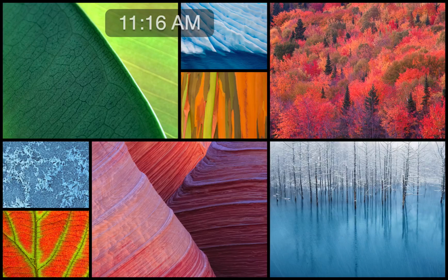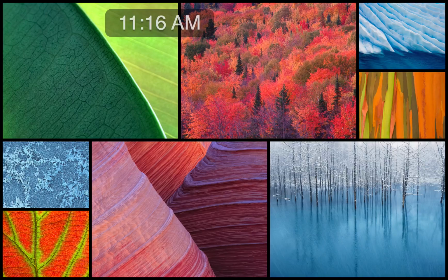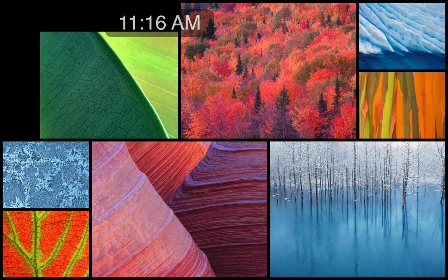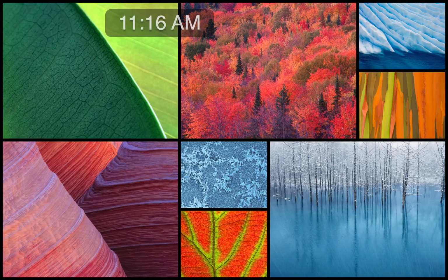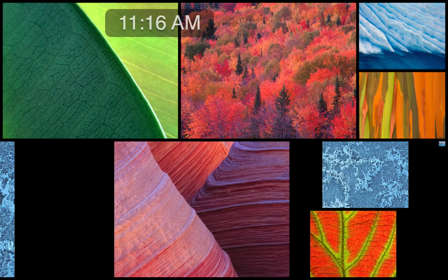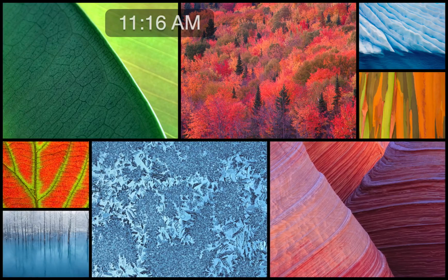Okay, so we're going to grab the 4x4 now. The good thing about this is if we do it correctly, we can get the weight of our building, okay? So that's why if we put everything in the model, we can generate schedules and we can weigh this thing and figure all this stuff out. So I'm going to overwrite the existing one. Oh, it already had this. It does not like that.